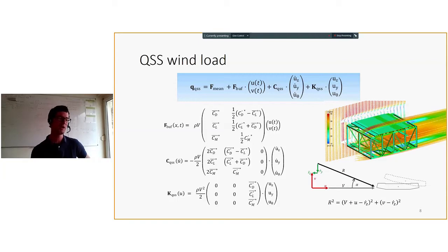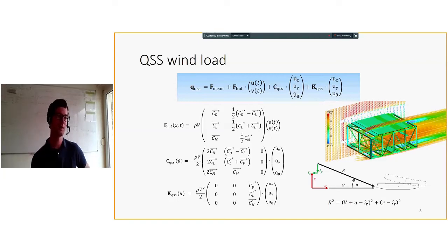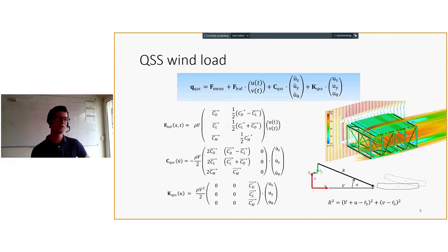When you measure the aerodynamic forces on the moving objects, those matrices get full, and that's why this theory lacks accuracy, as well as being not suitable to predict any aeroelastic coupled flutter phenomena and so on. But it's a good starting point for investigating wind buffeting effects, for example.